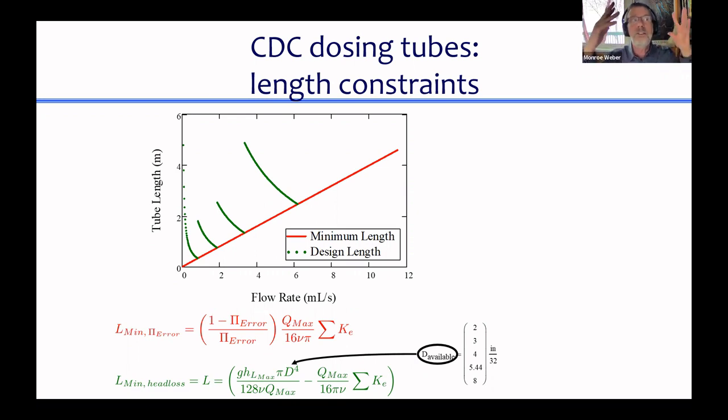So it actually costs you money every time you add more head loss to the plant. So that's one reason not to make the head loss really large in the linear flow orifice meter. So then what's as small as it can be and still have it work nicely?